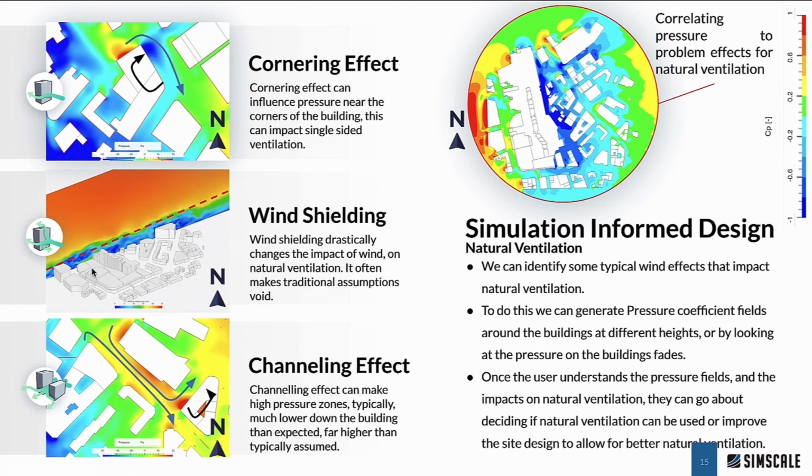Wind shielding, as I mentioned, this is a huge area of shielded urban landscape that's been generated by this shopping mall. And you can see all these fluctuations, these low speed areas, where the building of interest, actually that one in the middle, is completely within this recirculation low speed zone. And that is going to reduce the amount of flow or flow potential through our room.